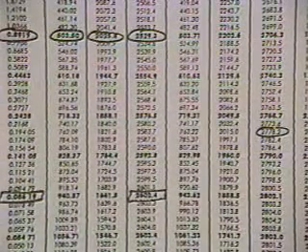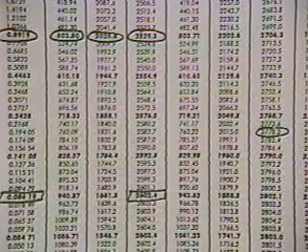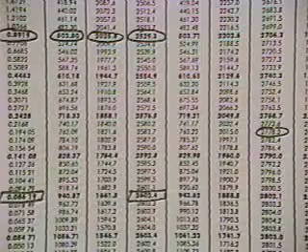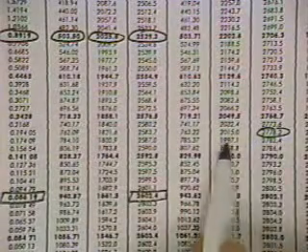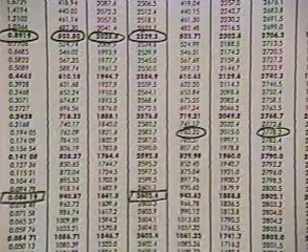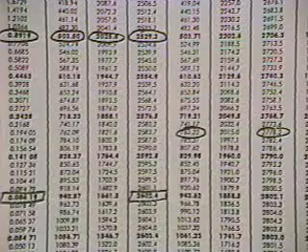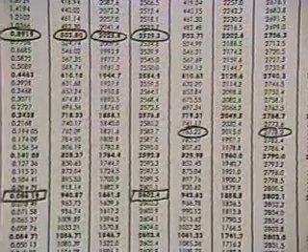And then we also know that it leaves the heat exchanger at state 3 as a saturated liquid condition, so we also can look up on the same 1.002 and find out that the saturated enthalpy is 763.22. And so this gives us the information we would need on the problem to plug it in and solve for the missing terms. Okay, so I've got this summarized on this particular page.